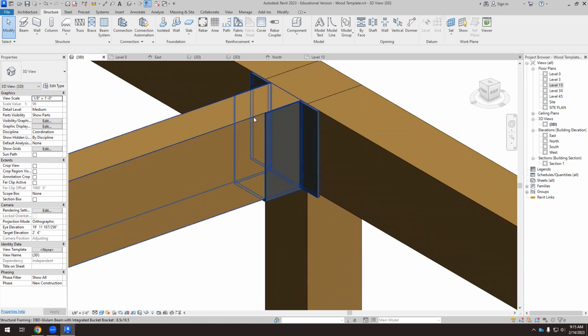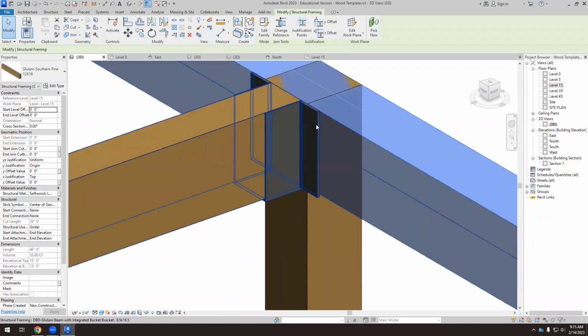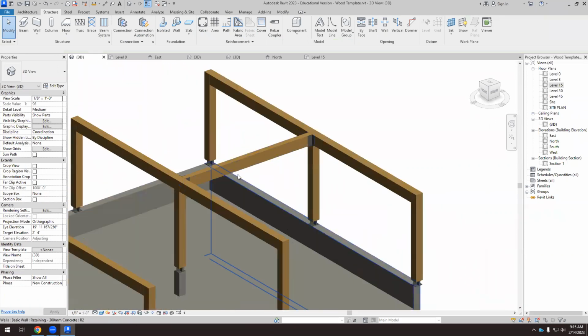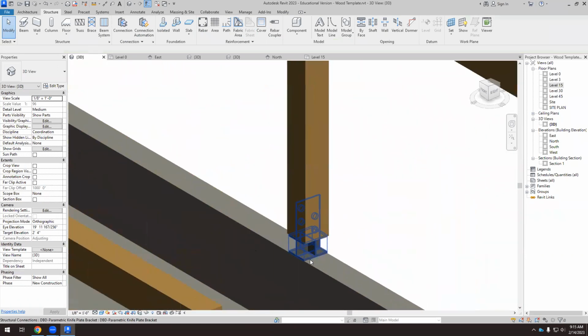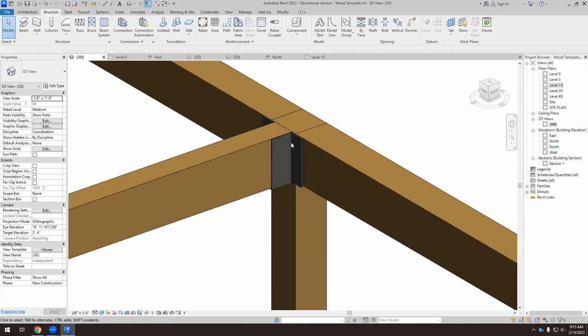Okay, so for the wooden beam, we always need this steel element to connect two different parts or elements of the building structure. We need this for columns, concrete walls, concrete columns, footings or whatever, and then we need this to connect two different beams there.